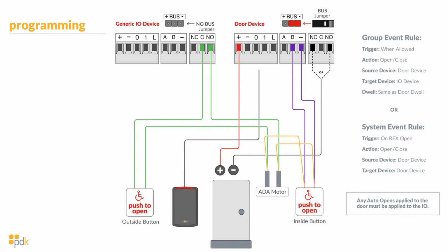We're going to focus on the outside. That's the secure side of the door. So when we activate the door device, the I/O device opens as well, and of course the door device opens at that same time. That's just a default part of the programming. We need to set both to have the same dwell time, otherwise we're going to have a discrepancy in the motor versus the button activation, and that's not going to go well for us.